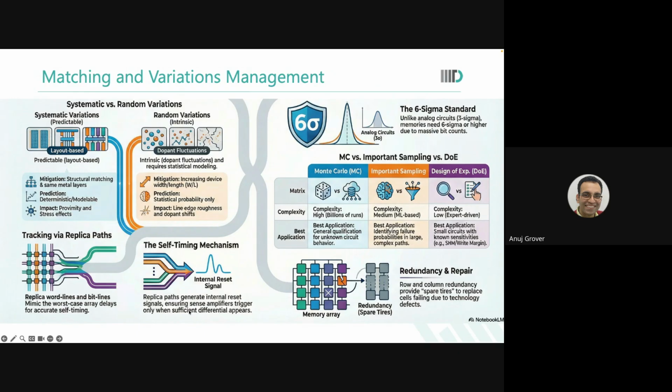So do not fixate on burst. Do not say that replica path is worst. Your only intent is that the burst cell should also pass. You have to use replica judiciously so that you are able to track that burst cell and ensure that this first step also passes, given all the variations that can happen. Are you with me? Any questions over here?